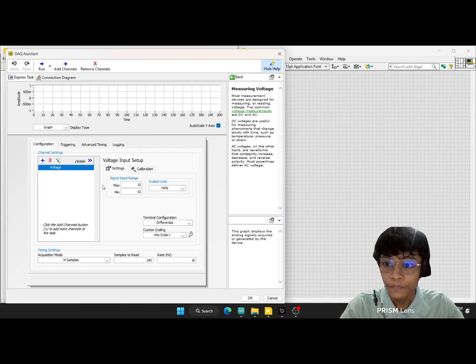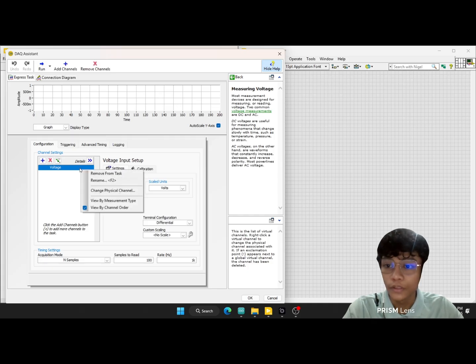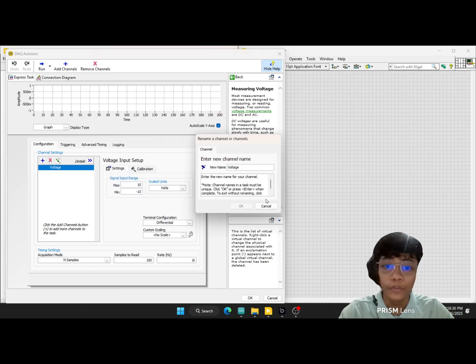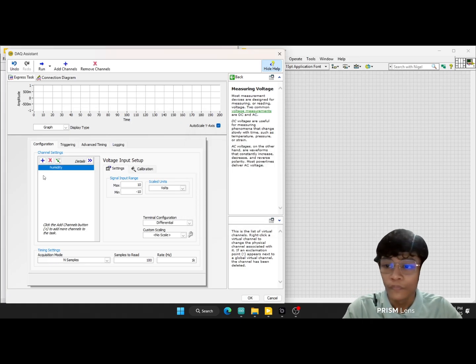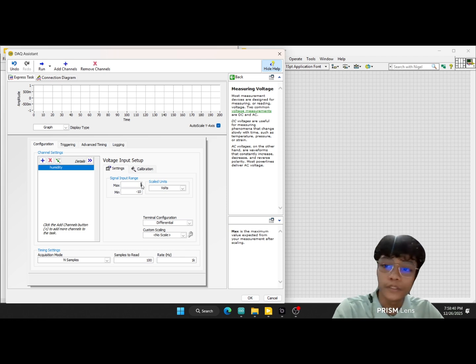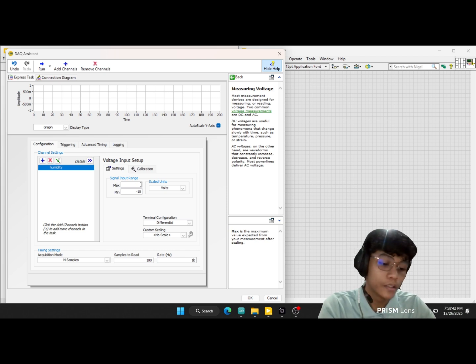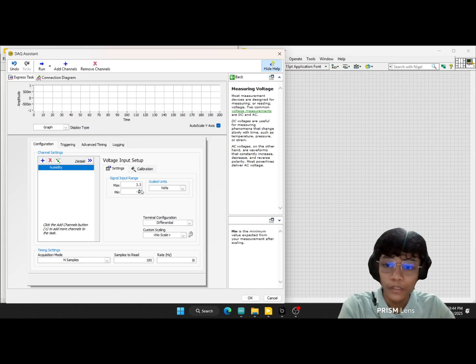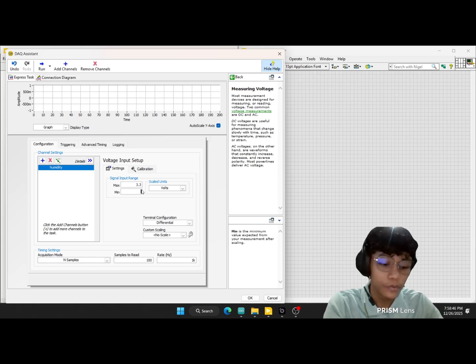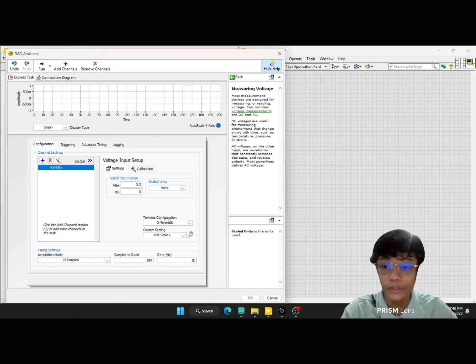Here we're going to change the name of the channel, let's say humidity, and the maximum and minimum value, because the ESP is going to send between 0 and 3.3, so we're going to change it right there.